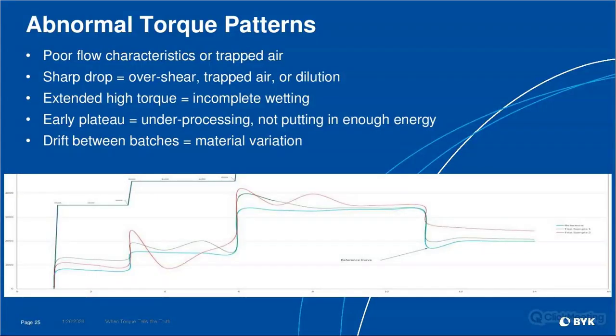Yeah. So from my experience, with regard to torque, that's kind of why we want to do these seminars, to get people trained into the idea that the torque measurement or the torque factor of the dispersion process is super important. What I see most often is people are just stuck on RPMs. Well, that's only one part of the equation, and your RPMs is only good if you have the correct tip speed, right? That's an equation based on the RPMs times the diameter of your dispersion blade.